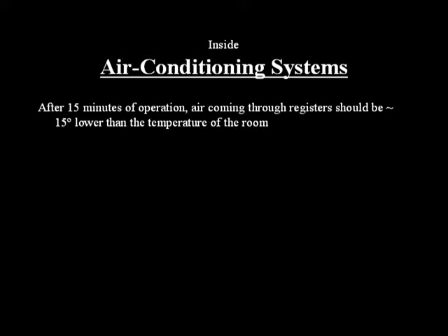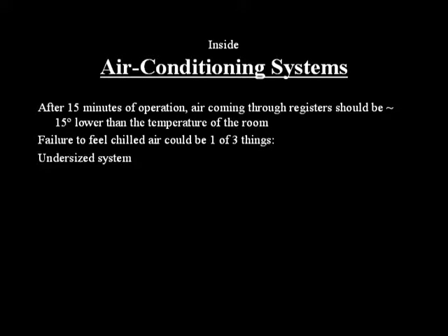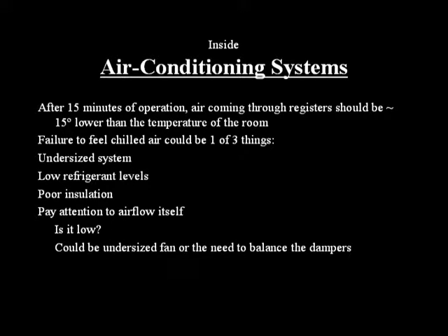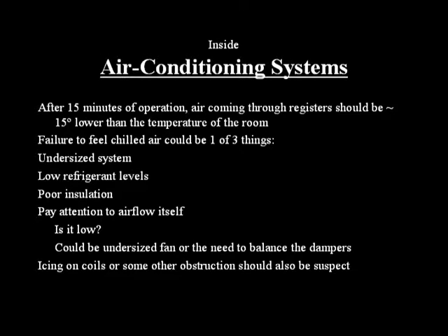After about 15 minutes of operation, the air coming through the registers should be at least 15 degrees lower than the temperature of the room. Failure to feel chilled air can be one of three things: an undersized system, low refrigerant levels, or poor insulation. Also, pay attention to the airflow itself. Is it low? This could be an undersized fan or the need to balance the register dampers. Icing on the evaporator coils or some other obstruction should also be suspect.